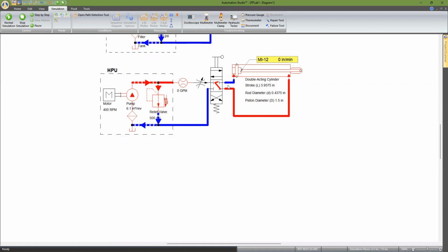And then during retraction, high pressure fluid was moving from this side to the rod end of the cylinder, and they could not get out when the retraction phase finished. Similarly, when I do the extension, you'll see the opposite. Red color in this part and blue color in this part because during extension, the pump was connected and now this fluid is trapped.